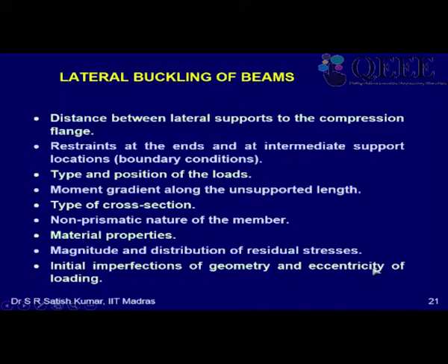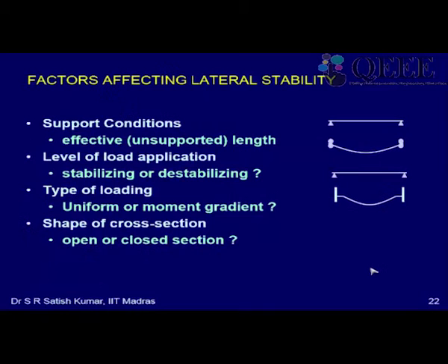What I mean by eccentricity is if the load is not exactly on the web, if it is on one side. Let's say I have a beam and I have a slab supported only on one side, then my load will be slightly eccentric to the center line of the beam. So then again I'll have some twisting, right?